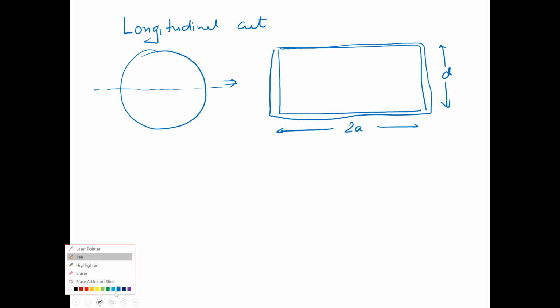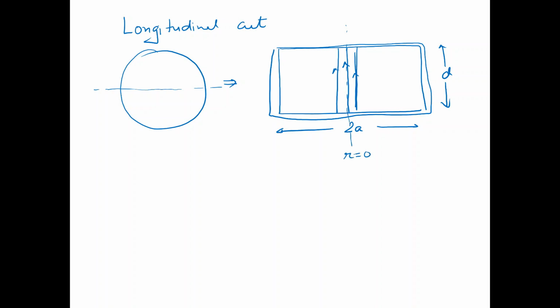And what this is telling you is that the electric field is pointing in Z direction. It is much closer in the center. This point in the center is r is equal to 0 point. It's much closer in the center, but as I go further away, this starts to spread out according to my J function. However, now if you notice in the vertical direction, this field can be supported. All this field is doing is putting some induced charges on the top and the bottom surface. That field is hitting the conductors at 90 degrees. So that field is still supported by the cavity.